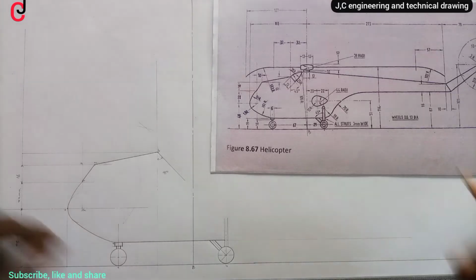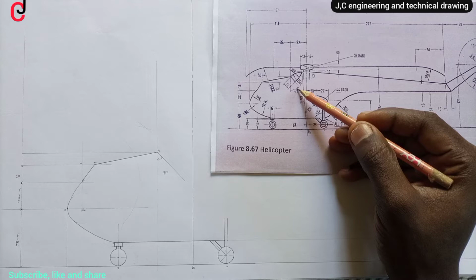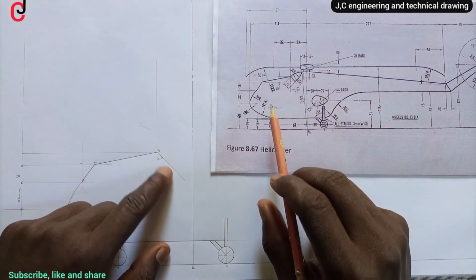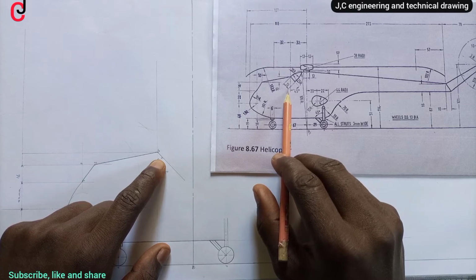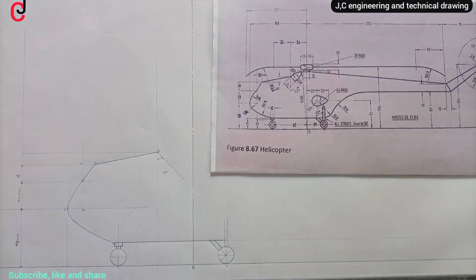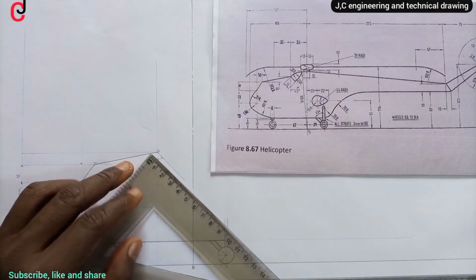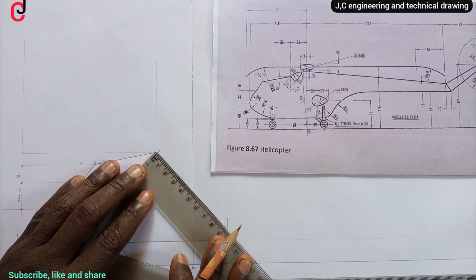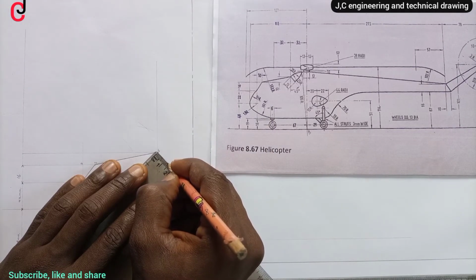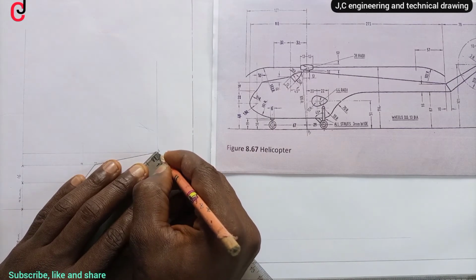Now from our 45 degree line, we are told that the total distance on the line we constructed is 13 millimeter. So pick our rule and we'll measure 13 millimeter on our 45 degree line. Measure 13 millimeter and then we'll outline it.